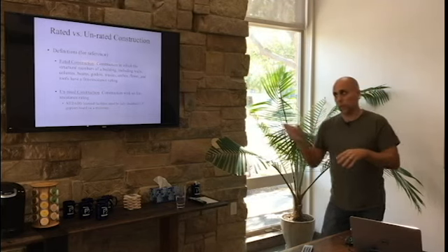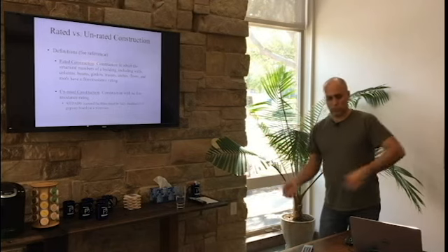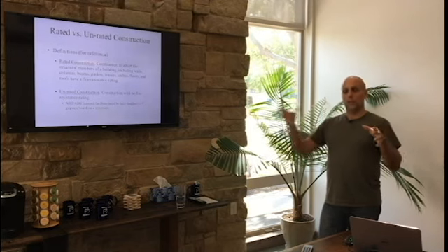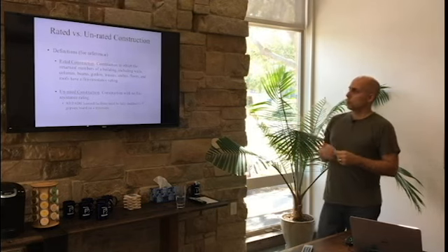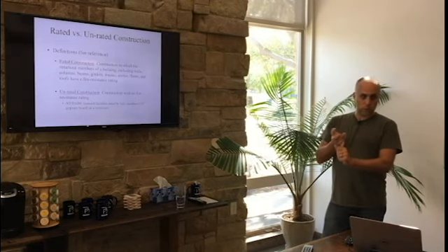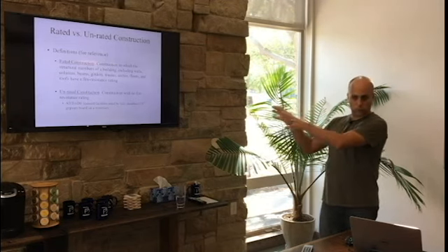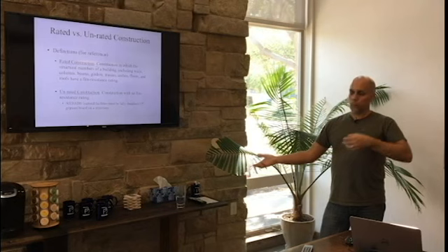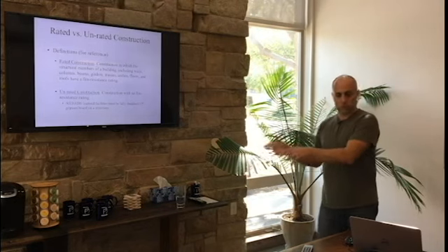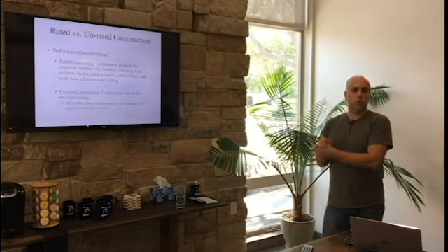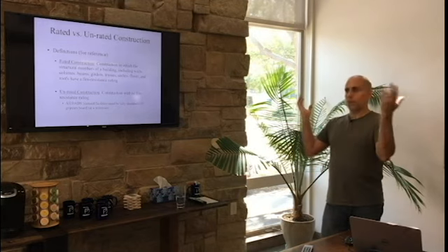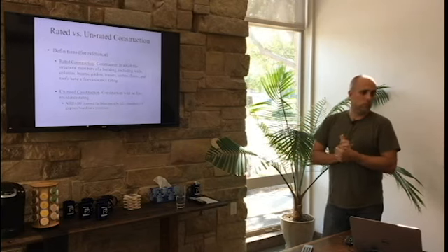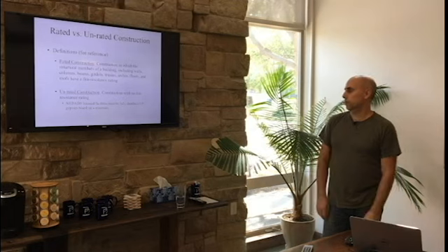Now, construction type, we'll get into a little bit, does care whether it's combustible or non-combustible, because even if it's not rated, it still has to match the construction type. But when it comes to do we have rated components to protect our structure, all we're worried about are those structural members, okay? Depending upon the type of building you do, you may have a lot of structural members. In a regular one story wood building, half the walls or more than half the walls are load bearing. You get into a steel building, none of the walls may be load bearing. So it depends on your structural system.